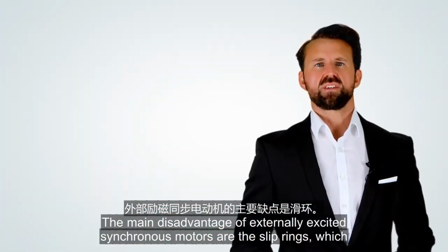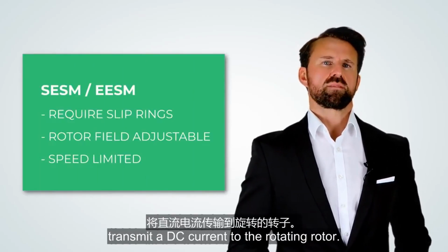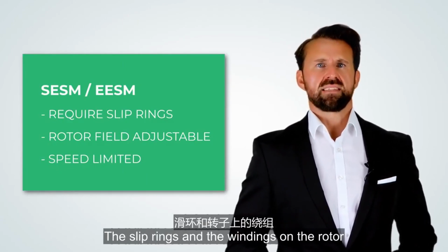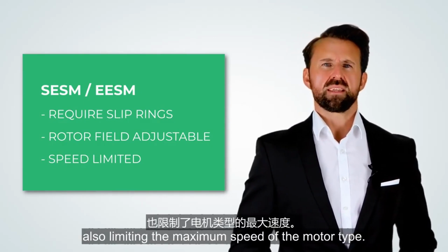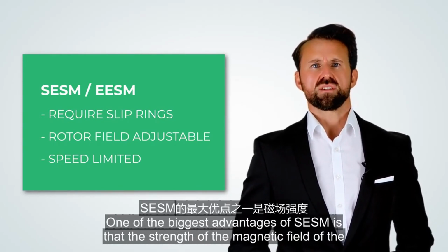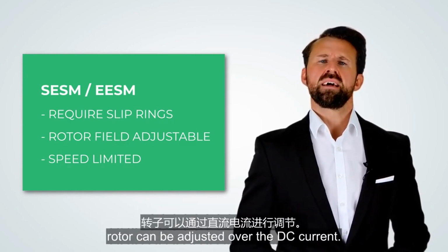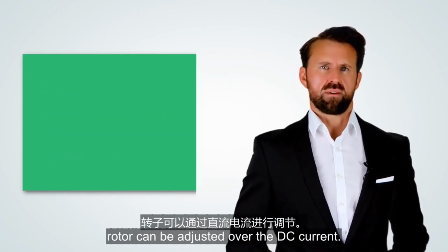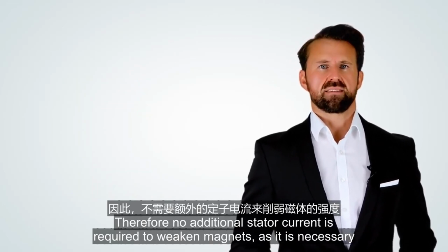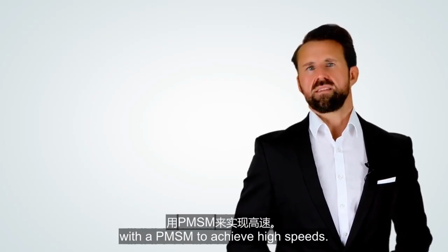The main disadvantage of externally excited synchronous motors are the slip rings, which transmit a DC current to the rotating rotor. The slip rings and the windings on the rotor also limit the maximum speed of the motor type. One of the biggest advantages of the SESM is that the strength of the magnetic field of the rotor can be adjusted over the DC current. Therefore, no additional stator current is required to weaken magnets, as is necessary with a PMSM to achieve high speeds.